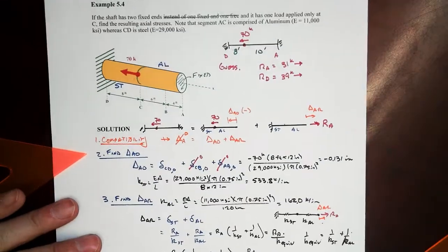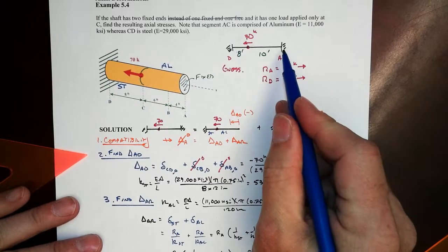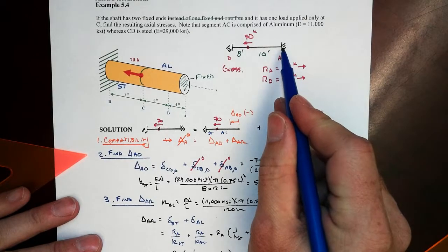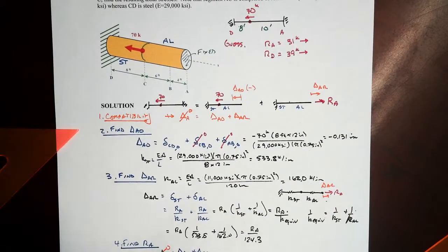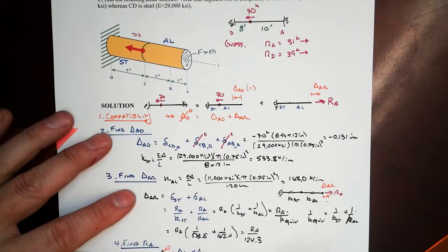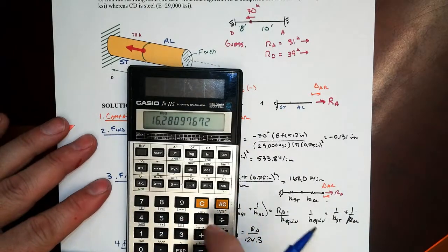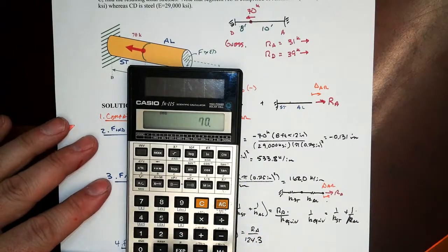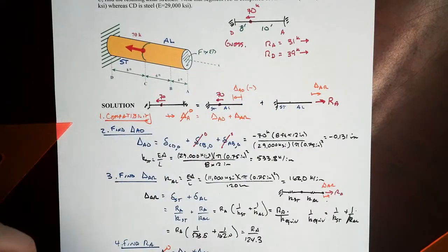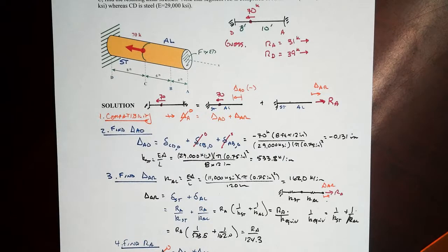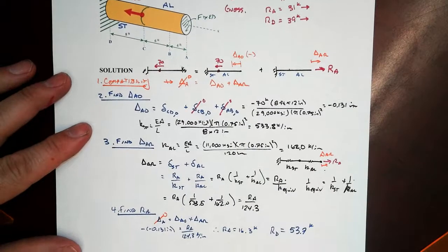Right? From a scale standpoint, then that sort of makes sense, right? It's smaller than 70. Now it's a lot smaller than what our guess was. That's pretty interesting. Our D will have to be the balance just from equilibrium, so that would be 53.7 kips. Notice I'm near the end, so I'm not keeping as many digits here and keeping a little bit more reasonable kind of numbers.